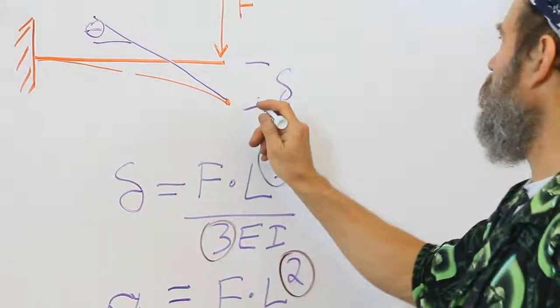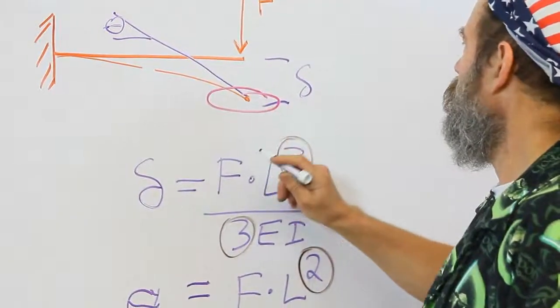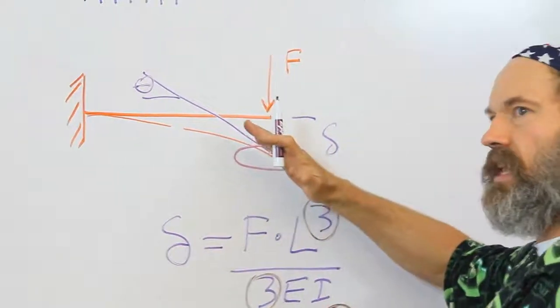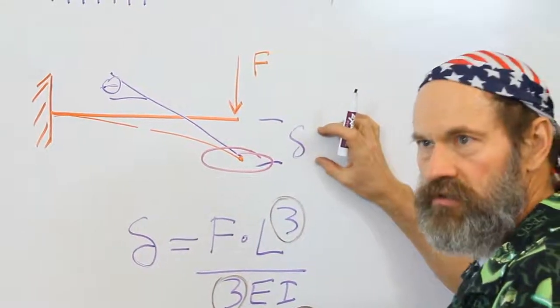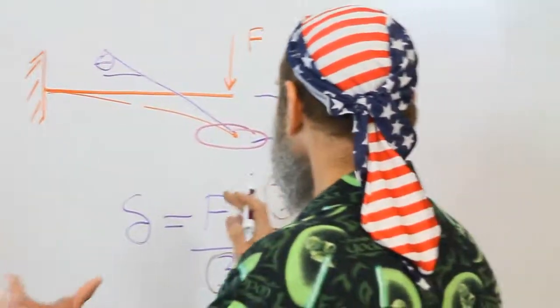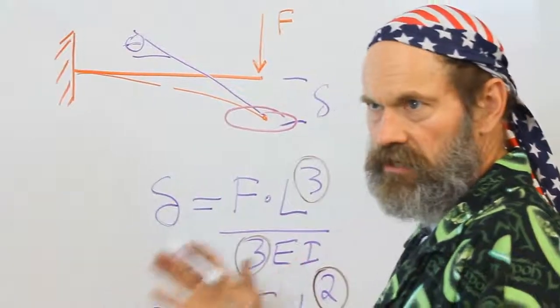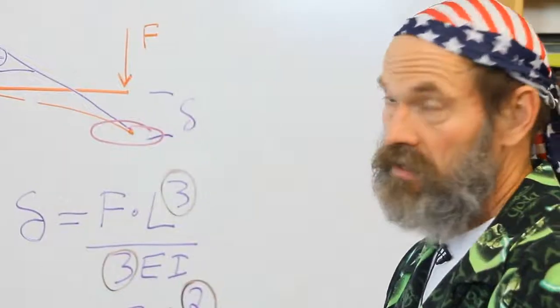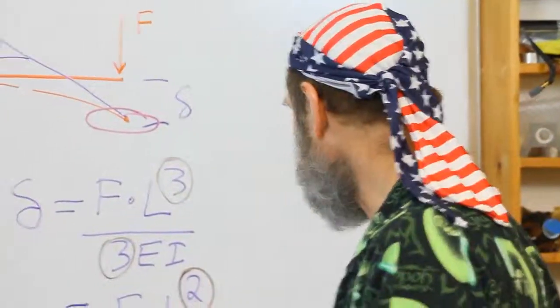So if I were to mount a lens here and push on the mount for the lens with a force F, I would get tilt in the lens and a translation. I don't want that. I want to mount the lens somehow such that I get pure rotation. This is what Bill needed to do for calibrating lenses. I believe it was for the SX70, which is one of the most brilliantly designed and successful cameras ever.